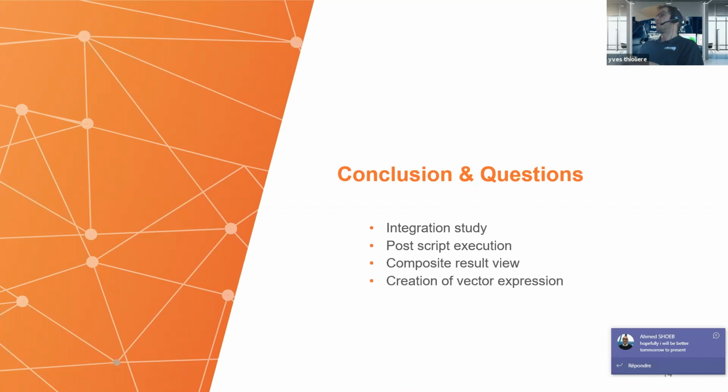First you run some calculation points, and then in the efficiency map creation you need to specify the DC voltage limit, and JMAG will search for the points working for this DC voltage limit and create the map that way, with that kind of algorithm.